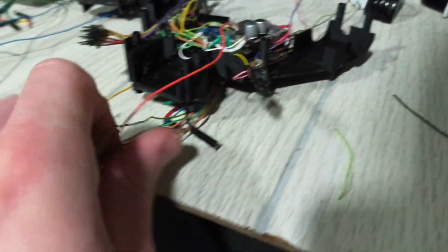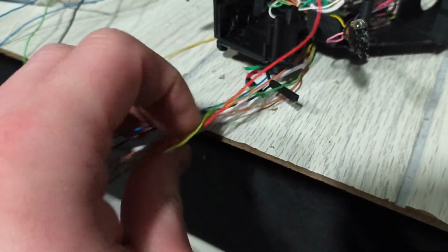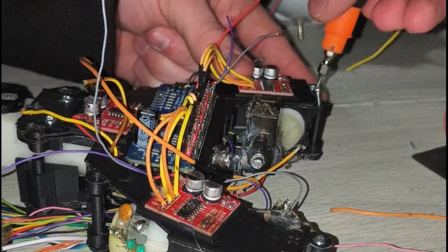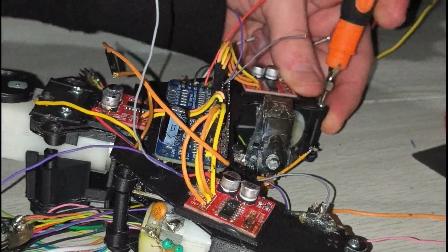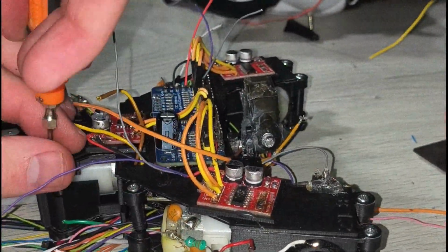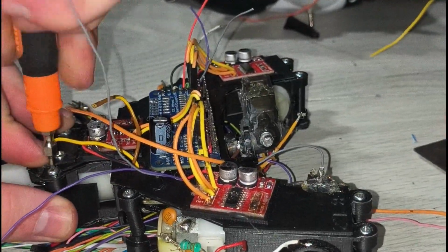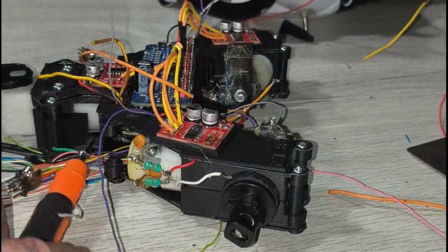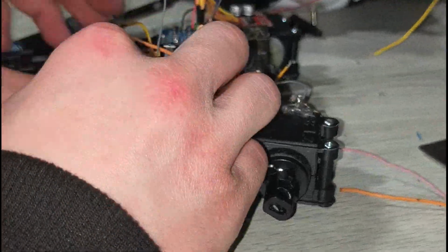Now, I hope that you've been keeping track of your wires, because if I didn't know what any of this was, I'd probably be freaking out. Now you'll pass the motor controller power and I2C wires through that back slot as well, and you'll put the front frame on and start screwing it together. Now be careful, or else you'll break the screw posts like I did, because I'm an idiot. Also, maybe try heating up your screws if the tolerances are bad on your 3D printer. Also, be sure to pass motor A and motor B from the arm connectors to the front.